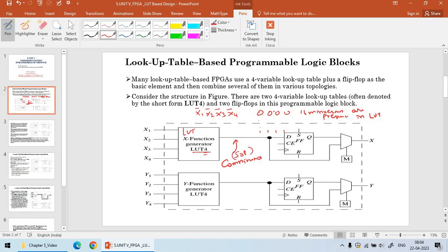You can take particular minterms as the output and sum them, and it is in the form of SOP. If you want to construct a sequential circuit, then you need a flip-flop, and this flip-flop is here. So this is the output of a sequential circuit.